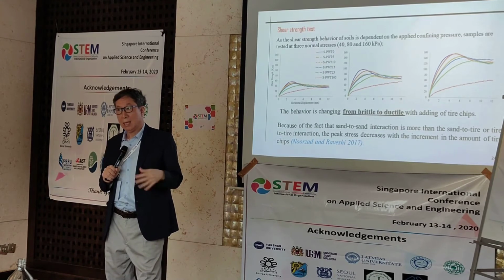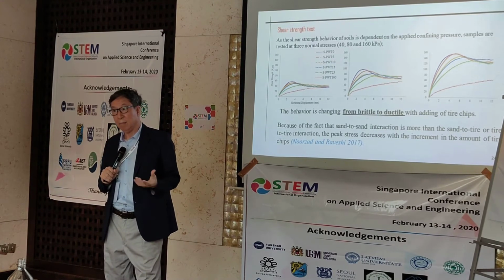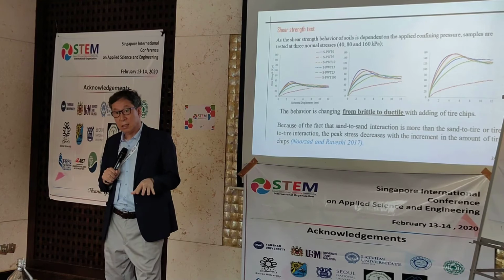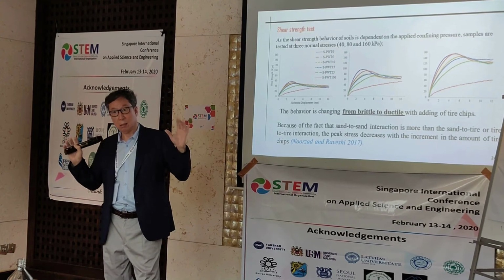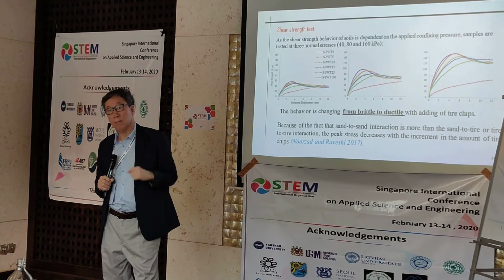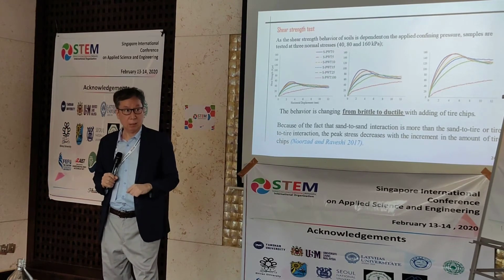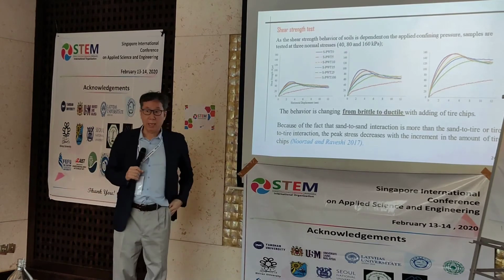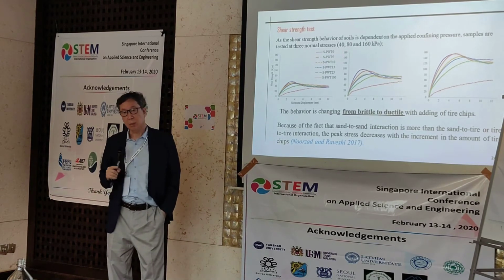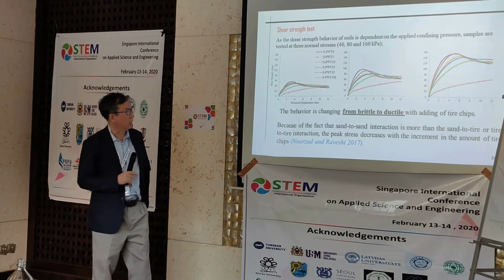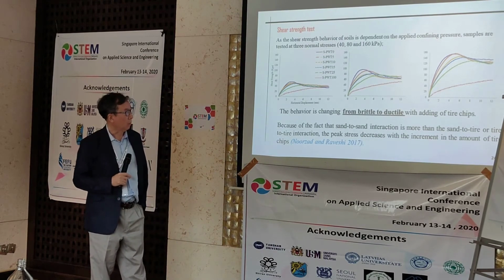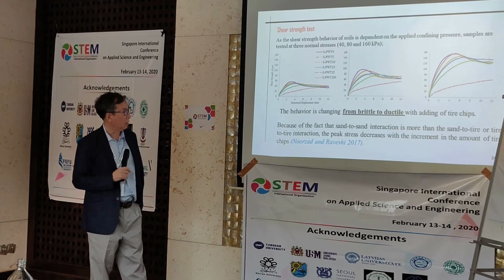So I can say that I can safely mix the TAC material with local soil, and it still shows good bearing capacity against the heavy load of the industrial facilities. So I checked the sorption capacity and also the bearing capacity of the soil mixture with the sorptive TAC. Next.